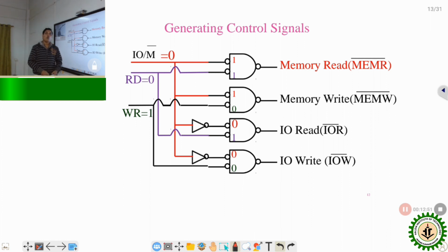That means when the microprocessor wants to read from an input output device or memory device, the RD signal goes low. Similarly, when the processor wants to write data to the memory device or IO device, the WR signal goes low. By default, both signals are high. That's why the RD and WR signals are known as active low signals.